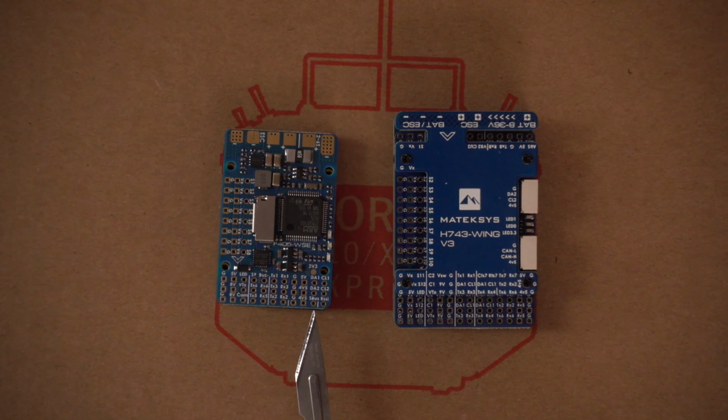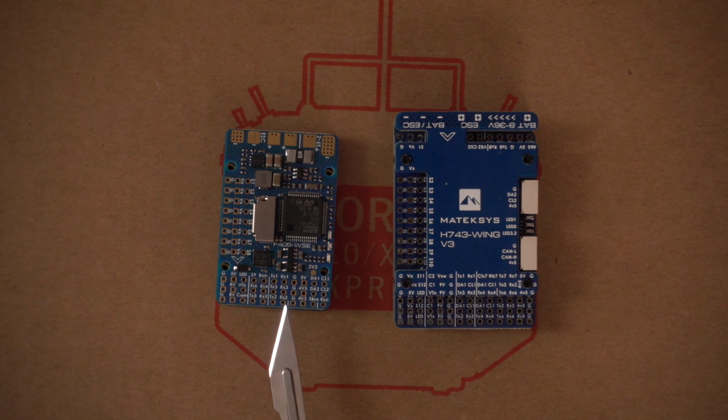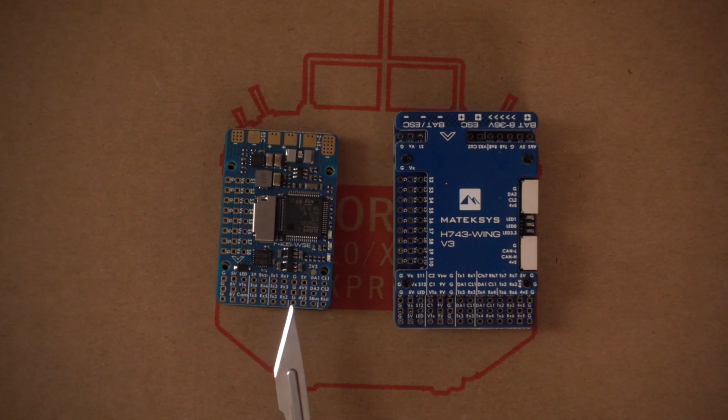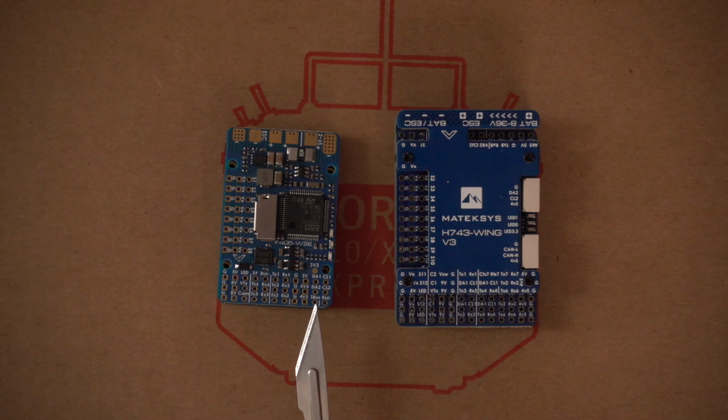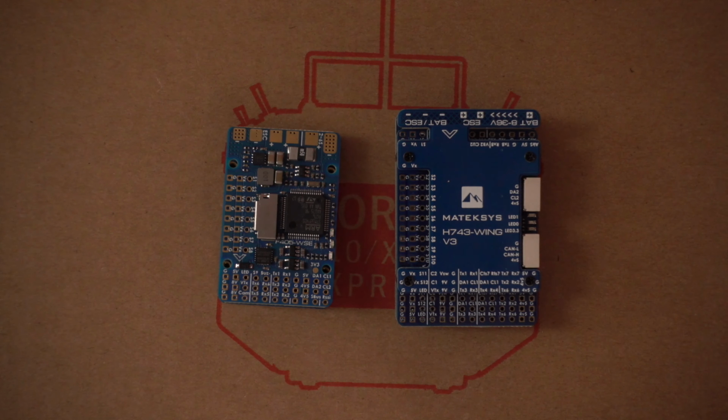Next to it we have an S-bus pad, which is basically going to be the same as RX2, but it has a hardware inverter in between the two. And what that means is it basically swaps the digital signal round, so zeros become ones and ones become zeros. It's just that FrSky receivers actually have an inverted signal compared to a regular UART, so to actually listen to it, we need to put it through a hardware inverter.